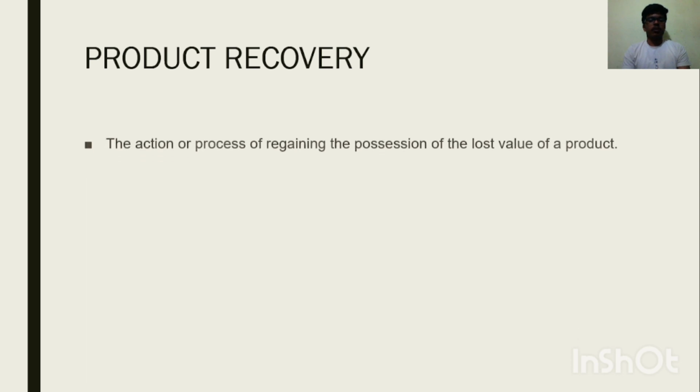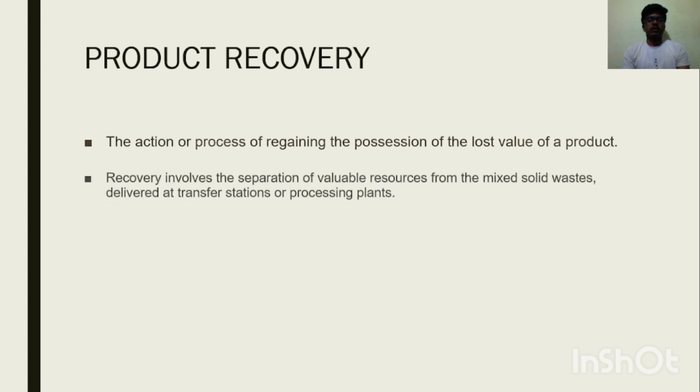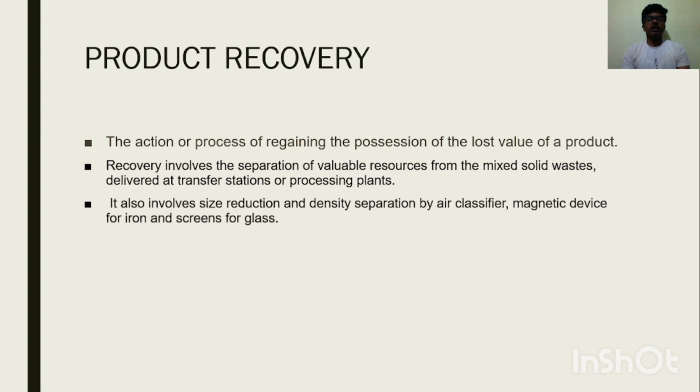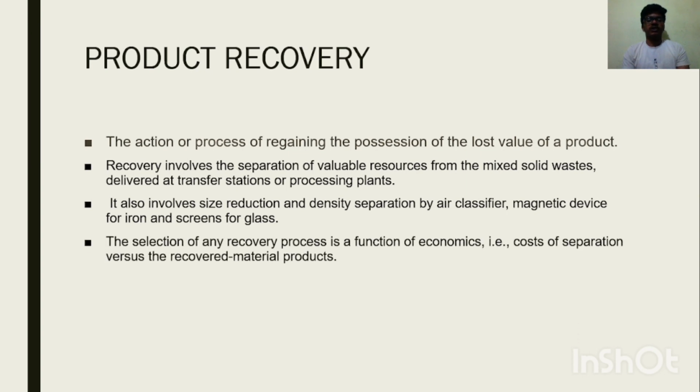First, let's discuss what is product recovery. The action or process of regaining the possession of the lost value of a product. Recovery involves the separation of valuable resource from the mixed solid waste delivered at transfer stations or processing plants. It also involves the size reduction and density separation by air classifier, magnetic device for iron, screens for glass. The selection of any recovery process is a function of economics, that is, costs of separation versus the recovered material products.